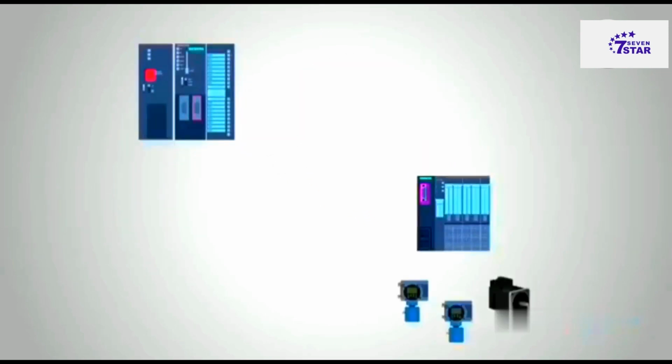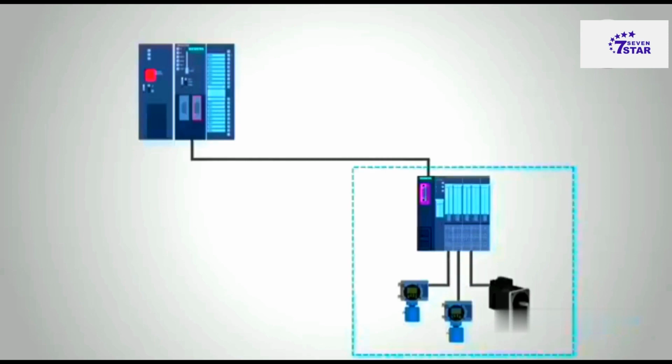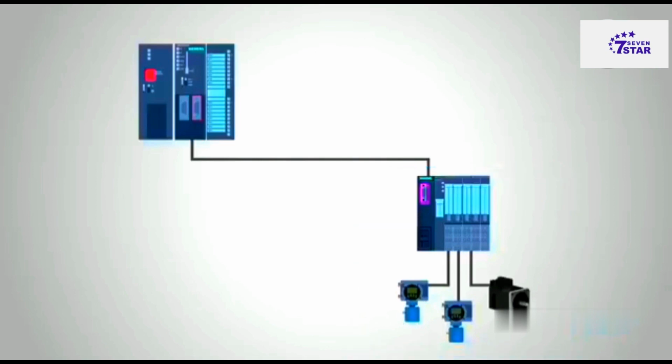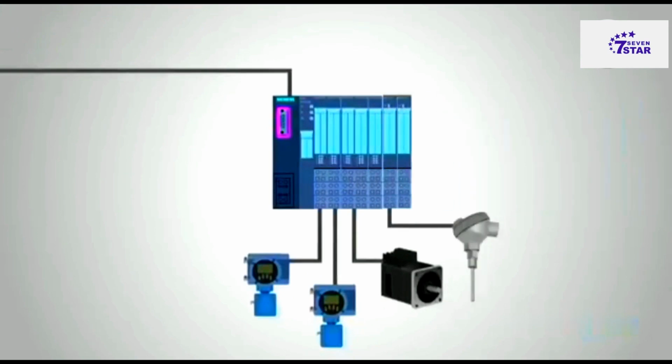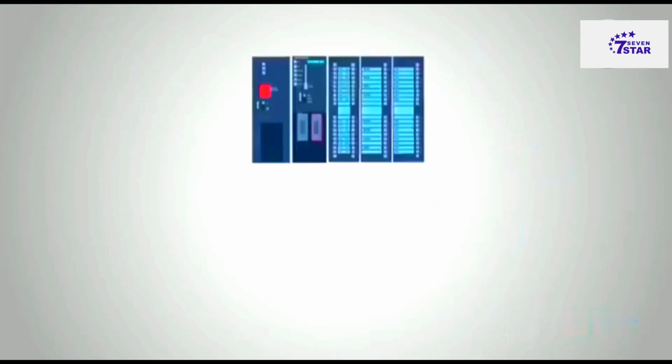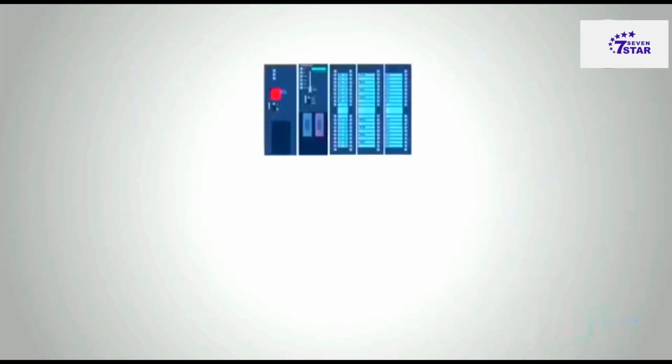Since the PLC is a computer, there is no need to limit it to only digital inputs and outputs. Over the years, the manufacturers added analog and other numerical inputs and outputs. Programming. To make these numerical devices useful, they included calculation capability in the programming as well, so that we can now calculate, for instance, statistical process control, SPC, values and put PID controllers directly into the PLC program.